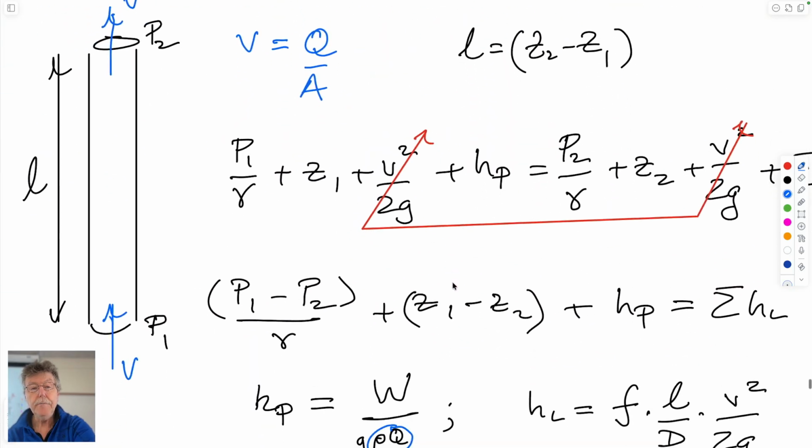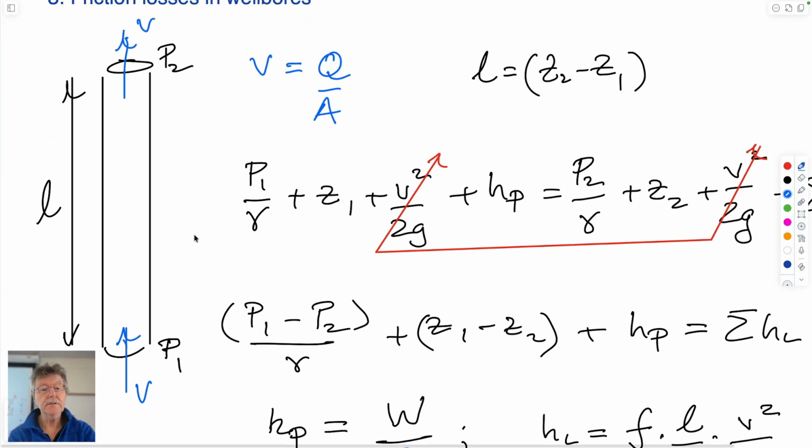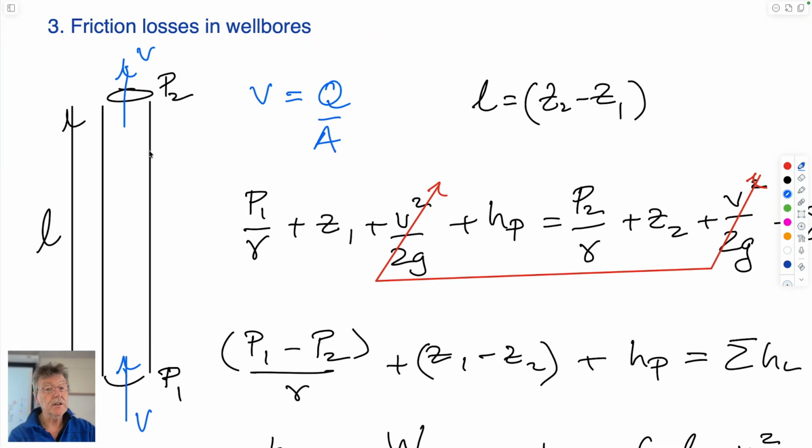Once you get it to the well, then you have to deal with parasitic losses. So frictional losses in the well bore are something that has to be accounted for. So it'll come in at some velocity. It will go out at the same velocity if the cross-sectional area of the pipe doesn't change. This would be the depth of the zone.